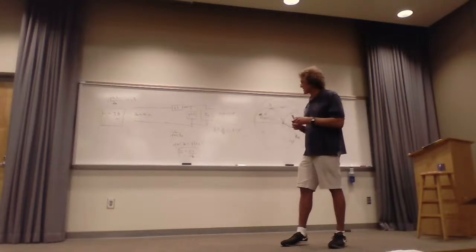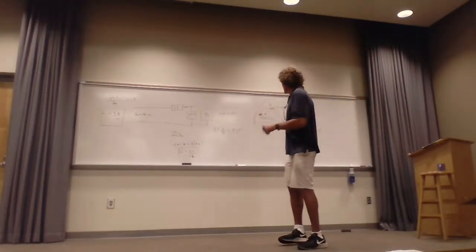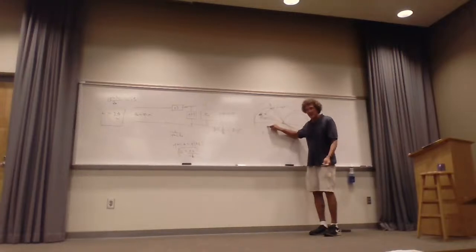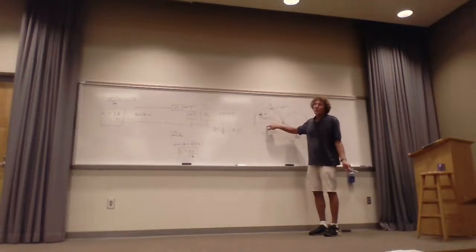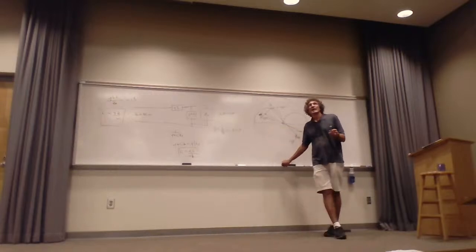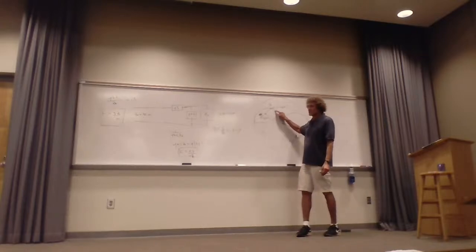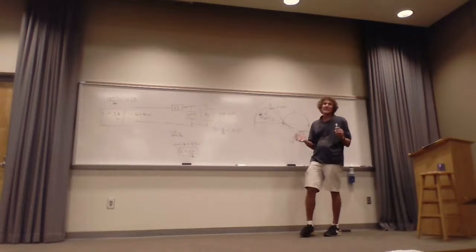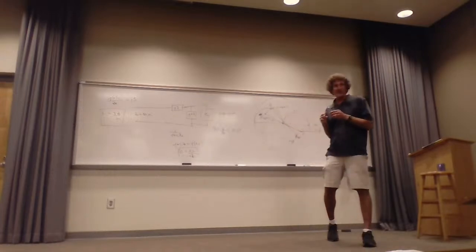I didn't get a chance to do one inside this, but if the normalized impedance landed inside the rotated circle, no matter what I added to that, I would add an impedance first to get it to this rim, and then I would add an admittance. So it'd be the opposite. Before, what I just did is what?